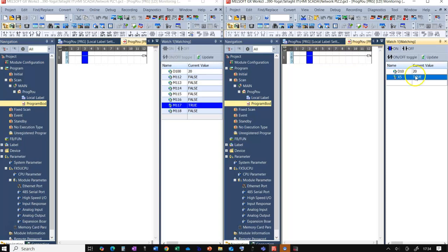So we're taking the X5 here and we're writing it to the other one. Now, as I see in that situation, we only need to set up that communication on one PLC. So we can either read or write. We don't have to set up a read and a write for the same thing. So we're either writing it to one or we're reading from one. And I suppose it's more of an operational decision as to whether we're writing or reading, or which way we're looking at it.